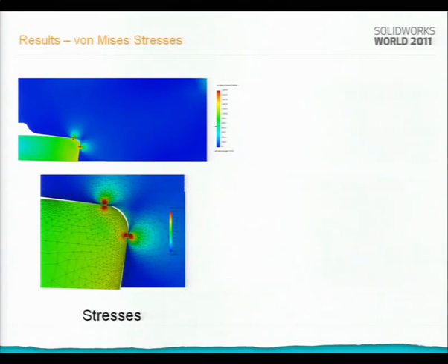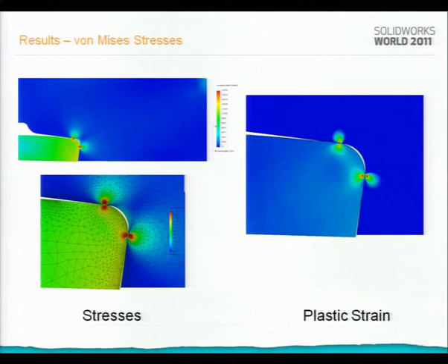And the result, finally, stresses. Of course, they are over the yield stress, but for this industry, for this application, it is the bread and butter, right? To have yield stresses. The point here is that the plastic strain doesn't cross the shear band, right? Do you remember the full scale test? I have the shear band. In this case, these are the permanent deformation. They are not crossing, so this model can be taken as okay. Yeah? This is the approach for nonlinear with plasticity.